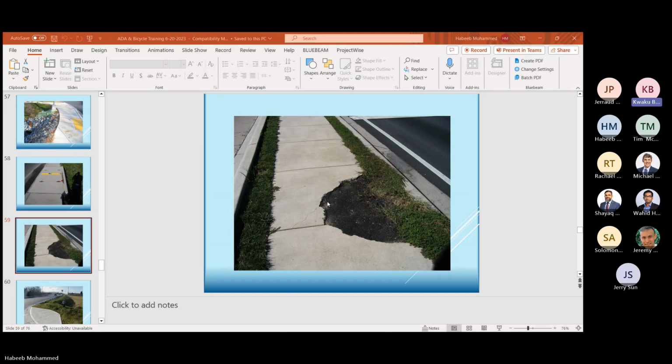Yeah, and I have dealt with a situation like this. On a huge job constructing driveways, we had to taper down the sidewalk to 32 inches so that the tie-ins wouldn't extend all the way back to their houses. So we provided a 32-inch sidewalk width every 200 feet in front of driveways to avoid significant impact to their properties. Yeah, you're right. Bump outs every 200 feet. You provide the bump outs.